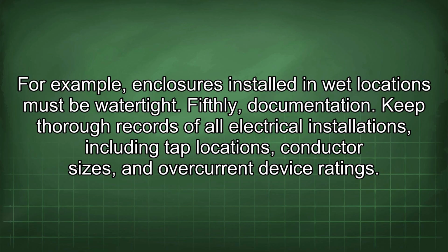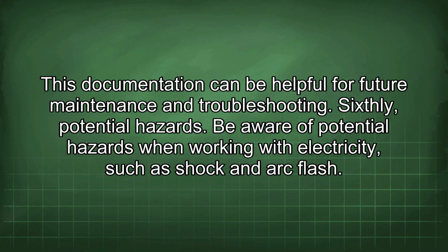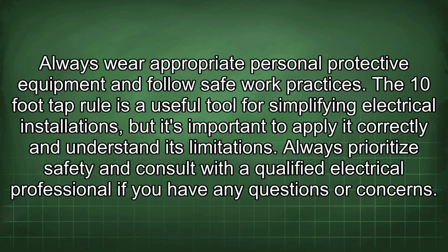Fifthly, documentation. Keep thorough records of all electrical installations, including tap locations, conductor sizes, and overcurrent device ratings. This documentation can be helpful for future maintenance and troubleshooting. Sixthly, potential hazards. Be aware of potential hazards when working with electricity, such as shock and arc flash. Always wear appropriate personal protective equipment and follow safe work practices.